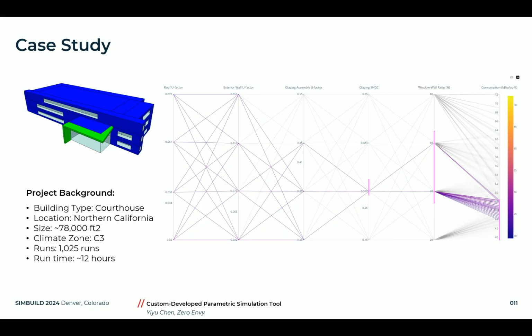For glazing solar heat gain coefficient, the design team was planning on designing towards 0.317. Now, just to clarify, that number is what we specified in the user interface. It doesn't mean it has to be that exactly. This number just needs to be within the constraints that the architect was interested in studying, and that applies to all the variables here.